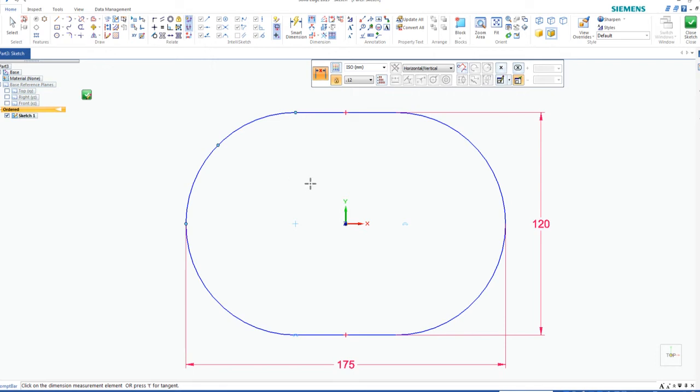Well, if we take a look at the front view, we have a dimension at the very top which says 7.5 millimeters, which makes it the center point of where the whole pattern is going to be. But then 7.5 millimeters to where the actual dome comes into play is the remaining portion, which is shown on the left-hand side of the front view. So 7.5 plus 7.5 equals 15.